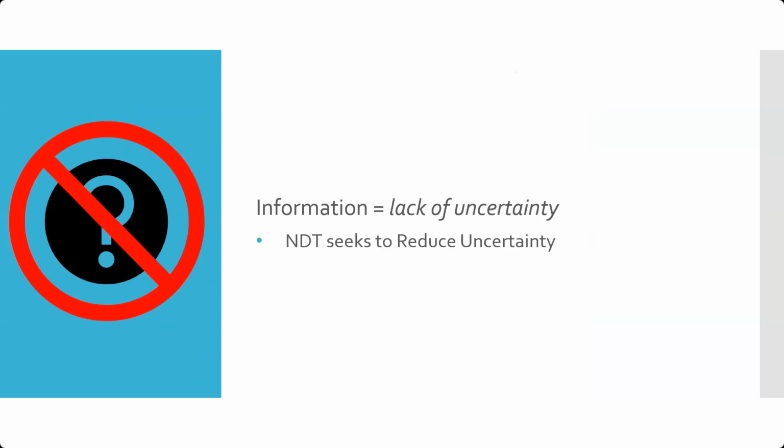You can actually have very, very small flaws, smaller than what's called a critical threshold, that are acceptable where an object or piece of equipment can be kept in service. We just want to make sure we're able to reliably find those flaws which exceed that threshold.